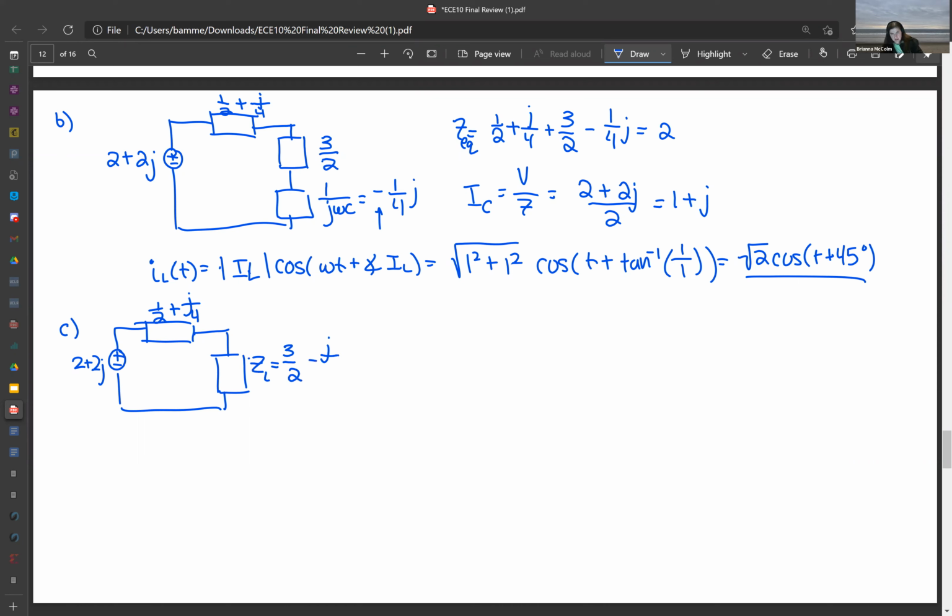And so we're going to use the complex power here, and we're going to find the power across the load. So this is going to be V times I_L conjugate. And then this right here is a voltage divider. So we're going to do Z_L over Z_L plus Z_S times the source here. And this is just V equals IZ, just finding the current and then taking the conjugate of that. That's what this star here means.